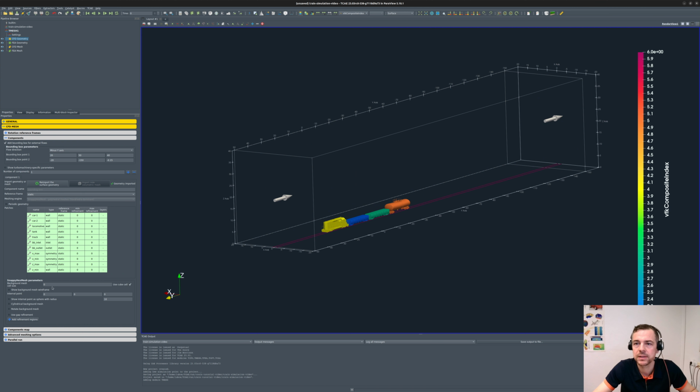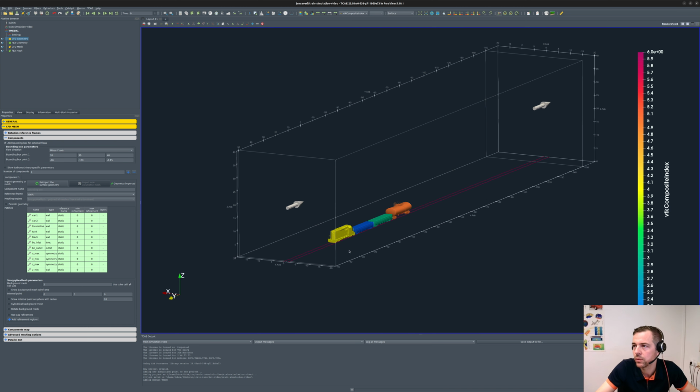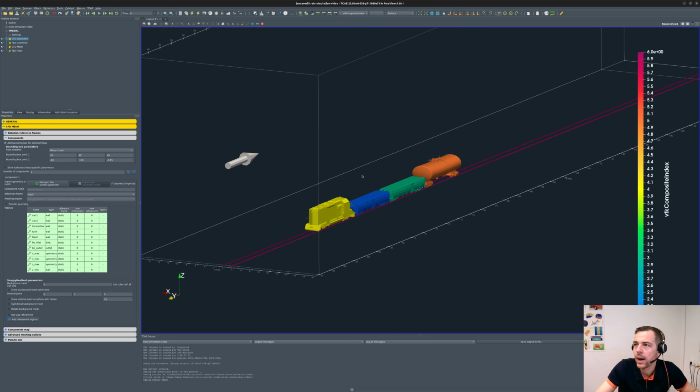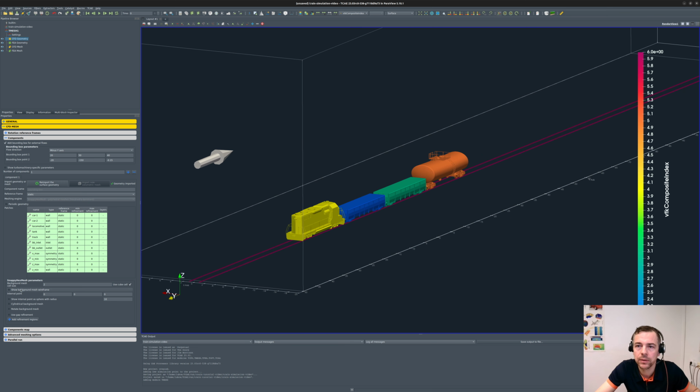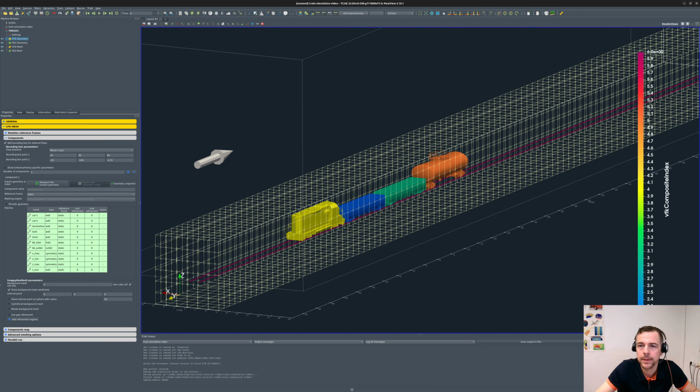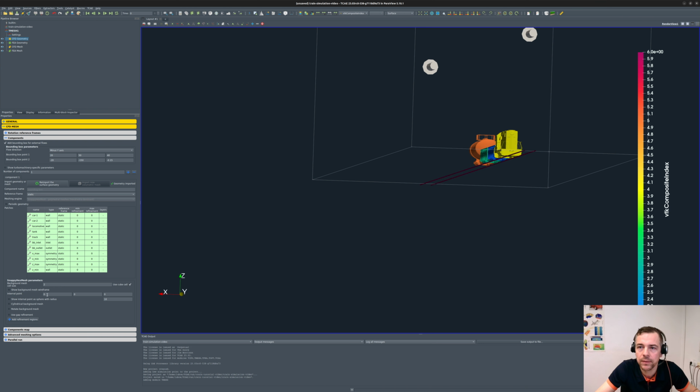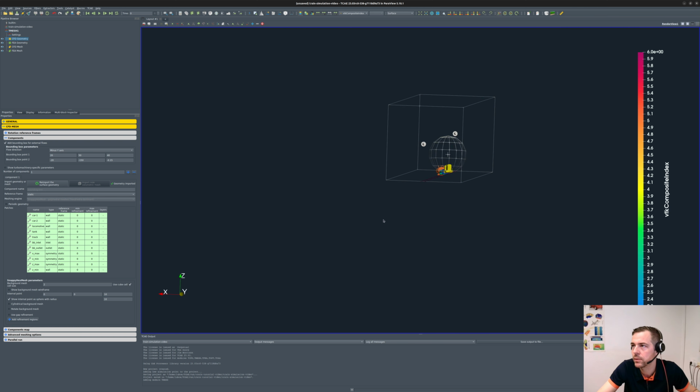Very important settings I need to do is the background mesh, which is the basic cube of the mesh cell. So it will be a cube of 2 meters edge. Every edge will be 2 meters wide. This is just an example to see what my basic cubes are. I'm fine with that, and I will also set the internal point in the domain to specify